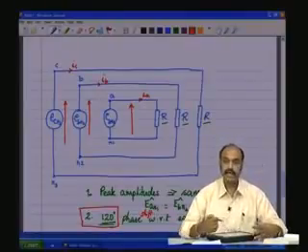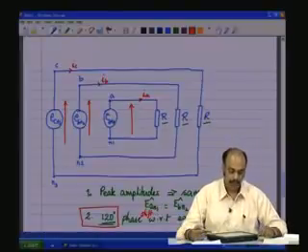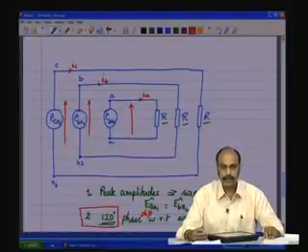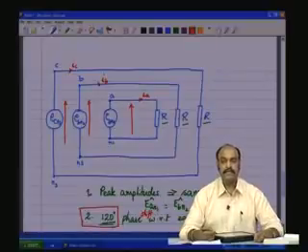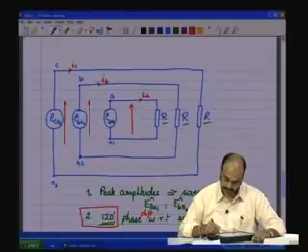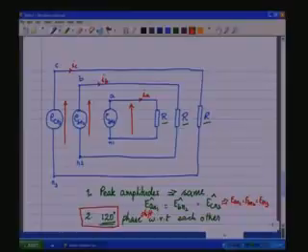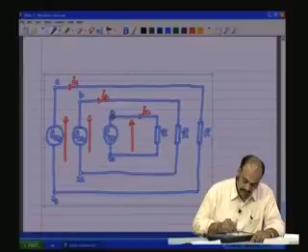So, which means that though electrically they are not connected, we have applied a constraint on the three source voltages, which is equal in amplitude, equal in effective amplitudes or the peak amplitudes, and the second is the phase displacement between each other should be equal, and which is 120 degrees. This also implies that we have the effective values of all three equal, the peak and the effective values. So, now we can make some conclusions here.